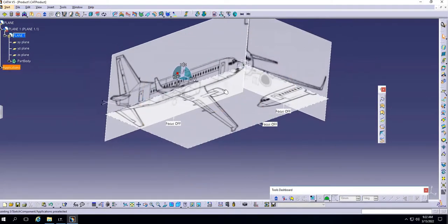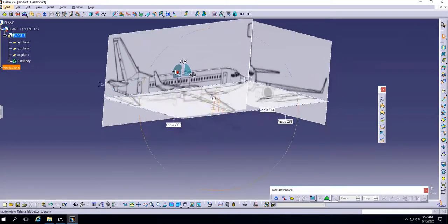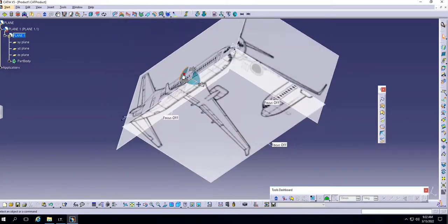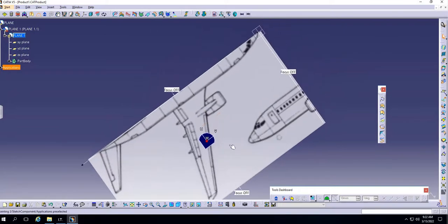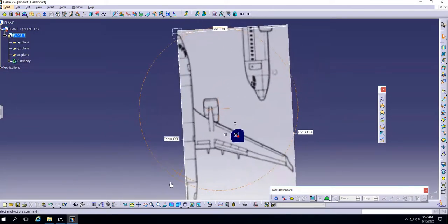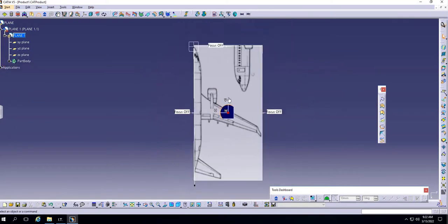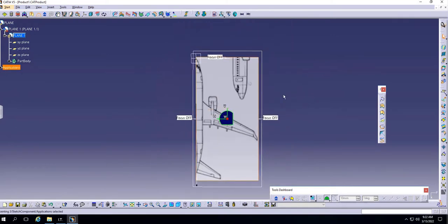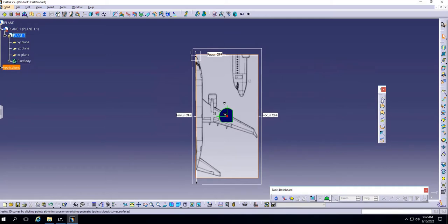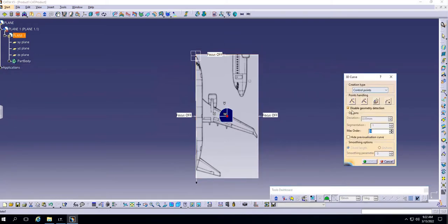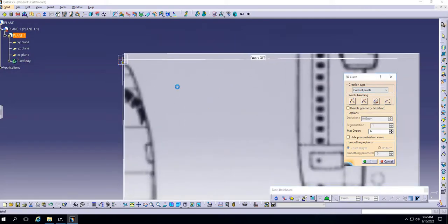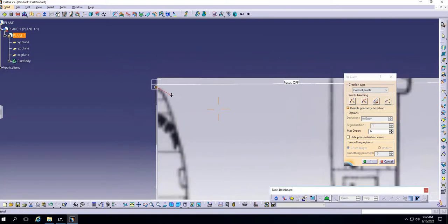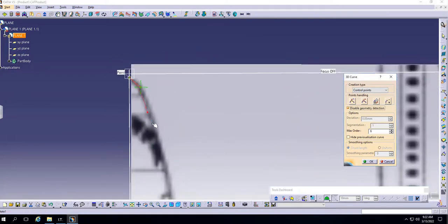And similarly, I'm going to make one more spline right here on this plane. So you would simply move the compass, put it right here, click on it, normal view. You can just move it according to yourself. Click on it once again, and again I'm just going to use 3D curve. Again, make sure to turn it off for the very first point. Zoom in. The first point is right here, and back. Turn it on. Really important to take into consideration.